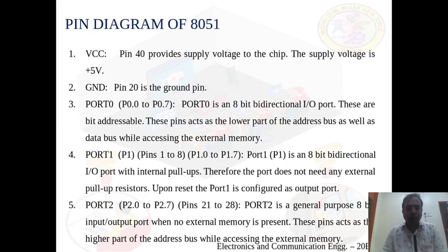The pin number 40 is a supply voltage pin. The supply voltage required here is plus 5 volt. This pin is VCC pin, and the pin number 20 is ground pin which needs to be grounded.